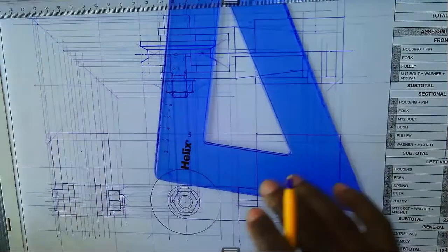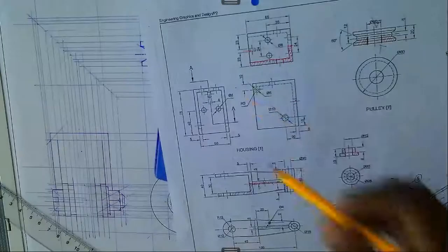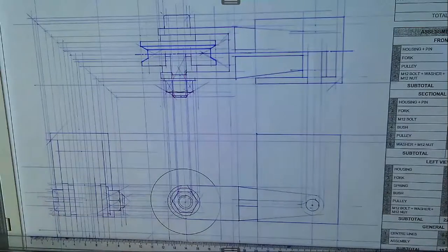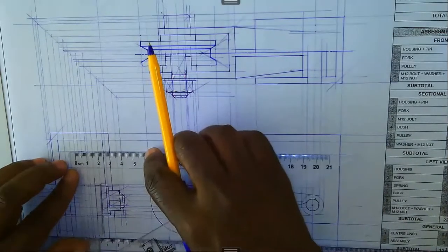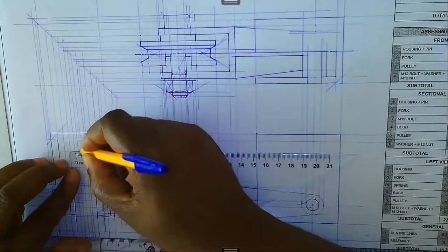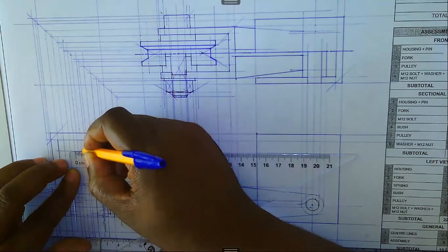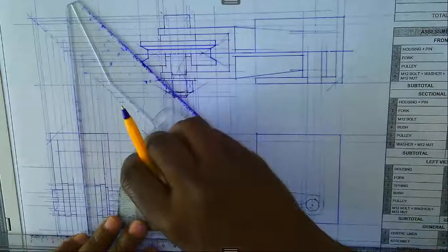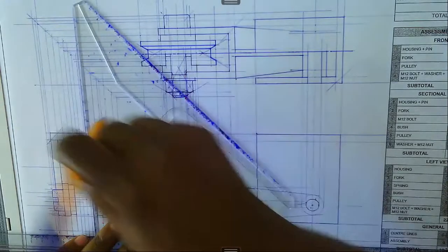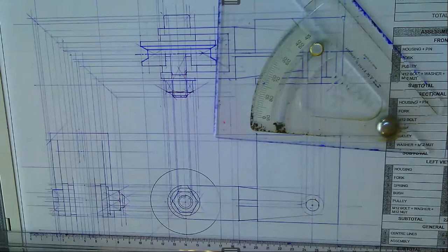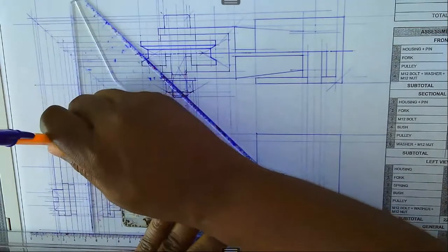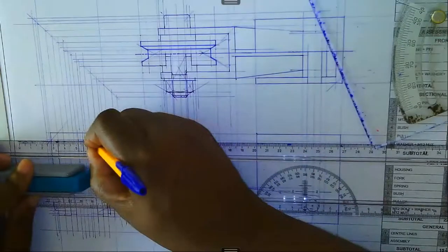Right, and the width of that, if we check again, right, you will see that the width is 4 millimeters. So we take this one, we draw a faint horizontal line like that. We measure either side of that, 2 millimeters, 2 millimeters. And we have got 2 millimeters, we have got also 2 millimeters like this. Like that. Then this is incorporated into that part, which we are going to outline like this. Outline like that. Then we complete this one now by doing this.